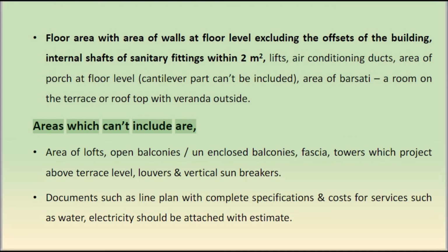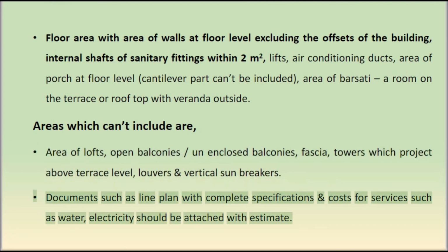Areas which can't be included are: area of lofts, open balconies, unenclosed balconies, fascia, towers which project above terrace level, louvers and vertical sun breakers. Documents such as line plan with complete specifications and costs for services such as water and electricity should be attached with the estimate.